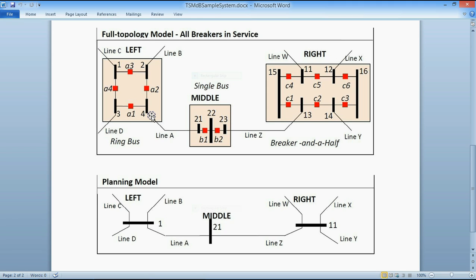You've got secondary devices that see currents based on this line flow, in addition to these branch flows. So you could probably do some form of hybrid, perhaps, and still use a database that's tailored for a bus branch model.